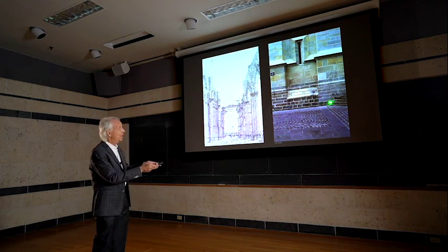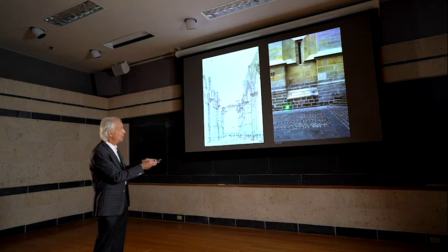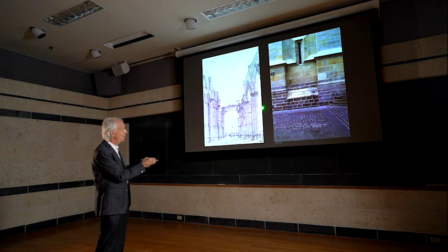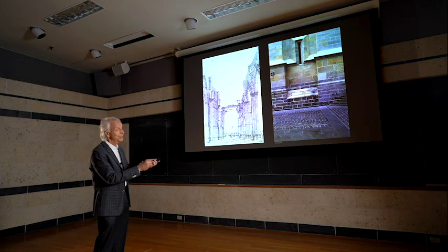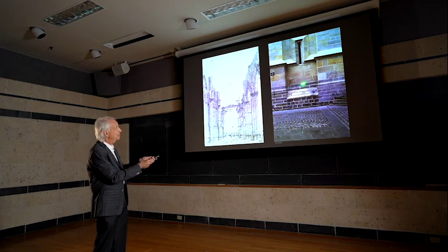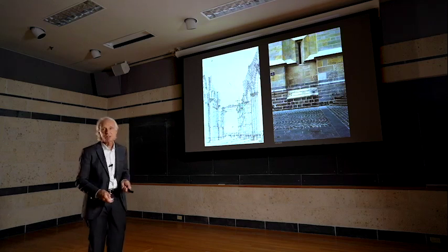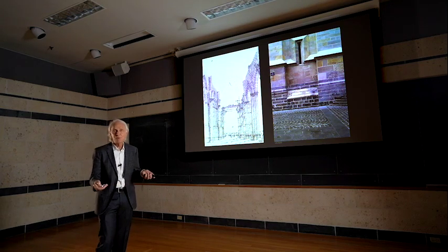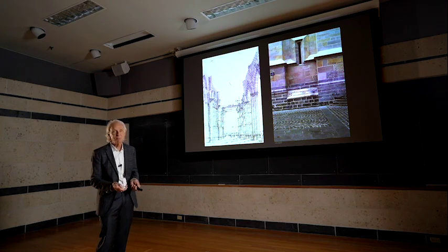They start out with one kind of limestone that's very dense and very resistant to moisture. So where it hits the ground, they're using this darker limestone for the foundation and up to a certain point. And then they're transitioning to a lighter and more porous limestone that's more beautiful, but doesn't have to contact the moisture of the ground. That limestone is fine. So we're building up, we're putting in scaffolding, we're taking the stones up, we're laying them up in a kind of normal way. And up to about 4 or 5 stories, that worked well with their normal construction process in medieval times.